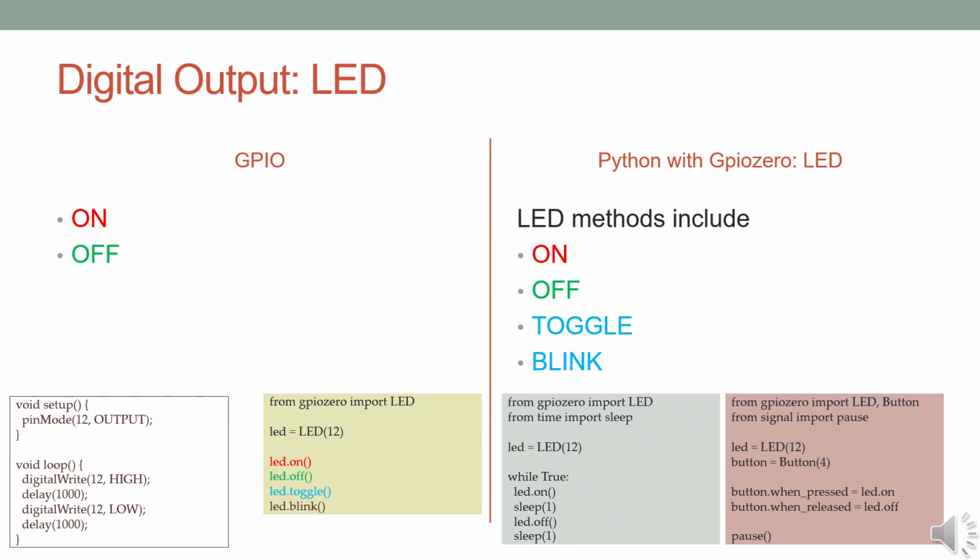Furthermore, in Python, these operations are non-blocking if desired, allowing the program to handle other tasks concurrently without complex timing logic. Using Python and gpiozero for LED control can be as simple as a loop that calls LED.on and LED.off with sleep intervals, but the real power comes from event-driven programming. By binding an LED to a button press, we can eliminate constant polling loops.